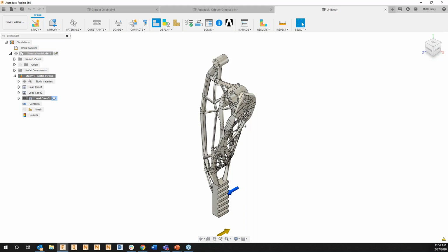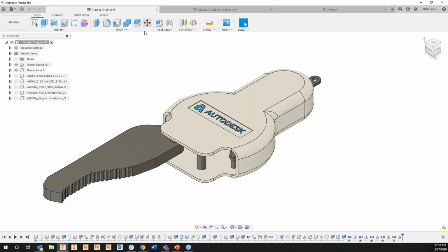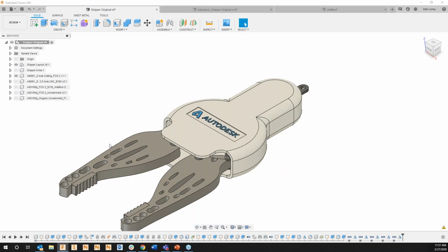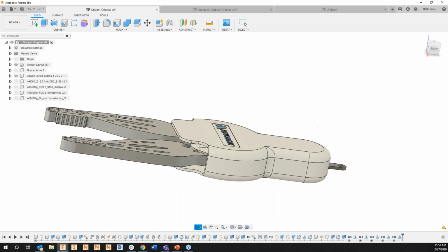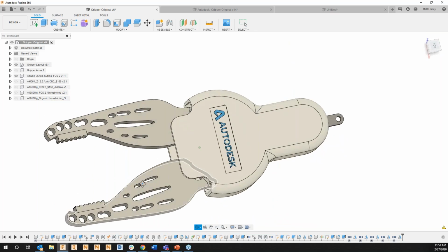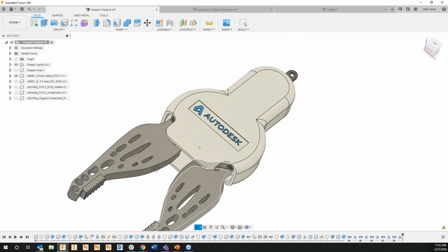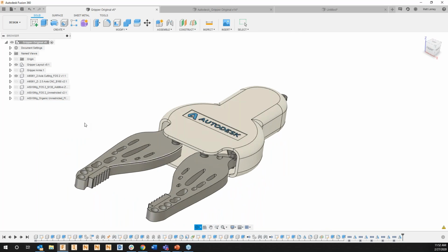So that's a quick walkthrough of setting up the generative design within Inventor, kicking it over to Fusion, running through the generative workflow within Fusion, sending out an output, and then validating. And just to quickly show you what some of these different manufacturable outcomes look like, this is the end of that robotic end effector itself. We can see we have the original component here. Next, we have an example of a 2-axis outcome just to really show you the range of solutions that we can produce. Again, this would probably be the most cost effective because we could really cut this out of plate.